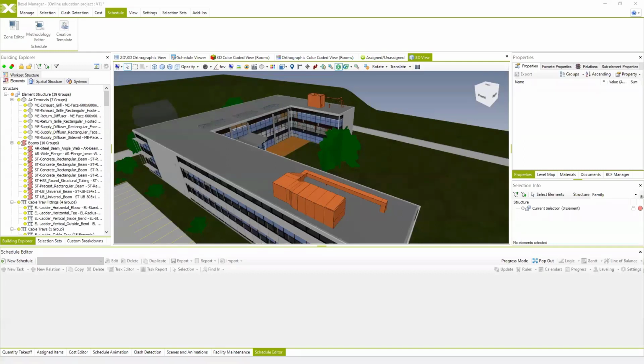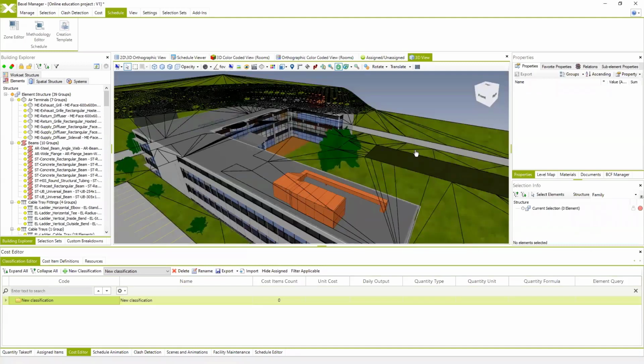And this workflow is not really the best or most efficient way of creating schedule, because you actually creating your tasks and estimating duration and your resources in some other scheduling tools, and then you link all these tasks in the BIM model, but actually your model already have a lot of information regarding the quantities, and if you used the cost editor and cost estimation, which we explained yesterday, you can automatically, let's say, anticipate the resources which are required for specific activities.